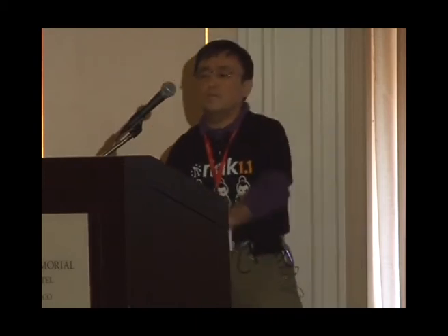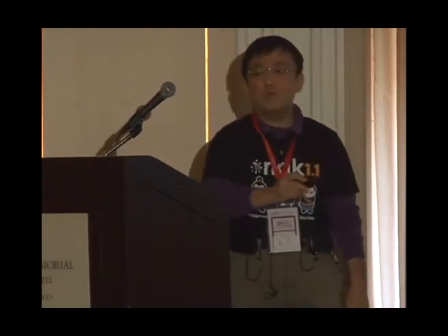And there's another type of protocol called WSPR, written WSPRnet, and it says Whisper. This is a very low bandwidth protocol. It takes 2 minutes to send only 50 bits. The speed is only 1.5 baud, and it sends 162 symbols, taking 110 seconds. The bandwidth is very, very small, only 6 hertz.